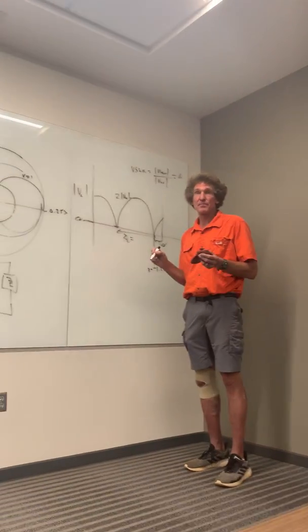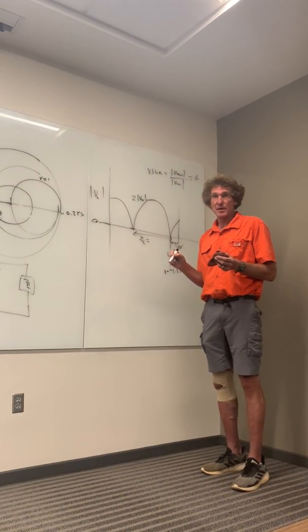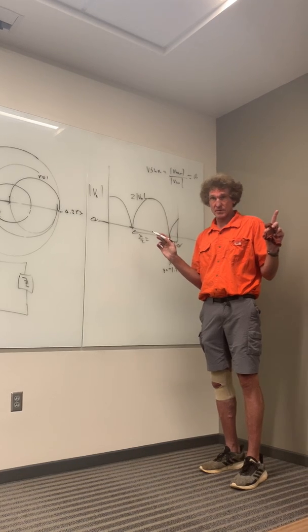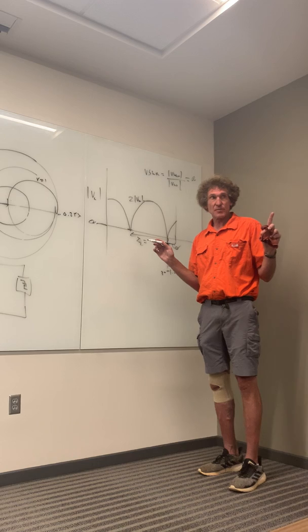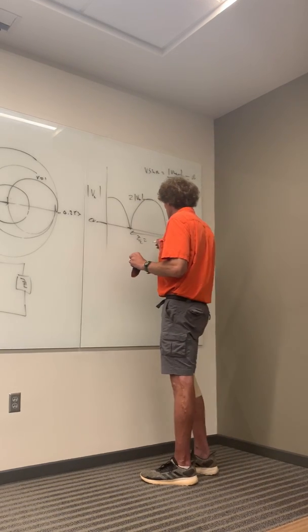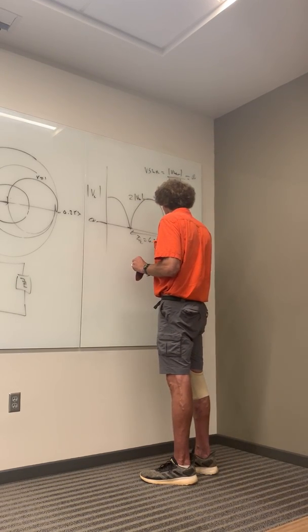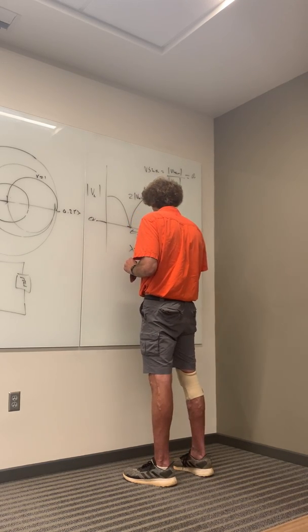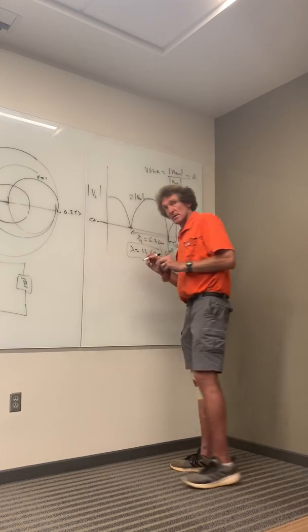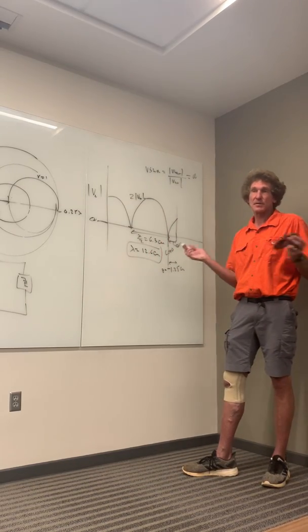This is a good problem. Everybody follow me on this? You look for the dead short to get the wavelength. The distance is like 6.3 centimeters. Anybody else confirm that? Now, I don't know if you can read that chart. If that's 6.3 centimeters, lambda is equal to 12.6 centimeters, right? Agreed? How do I get the frequency now?